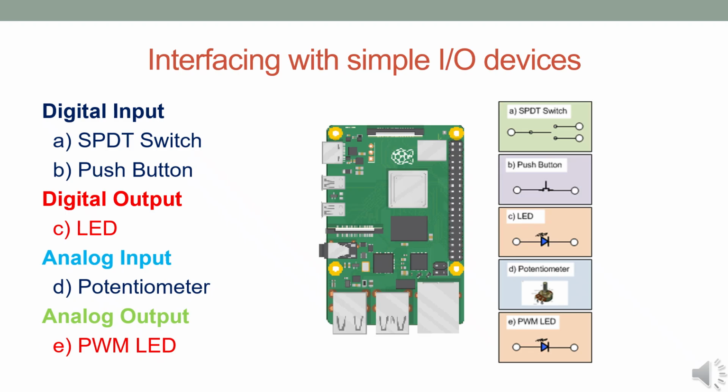This is particularly useful for controlling devices like dimmable LEDs or motors. With gpiozero's PWMLED class, for example, we can adjust an LED's brightness by setting its .value property anywhere between 0.0 (off) and 1.0 (fully on), allowing for smooth fading effects.